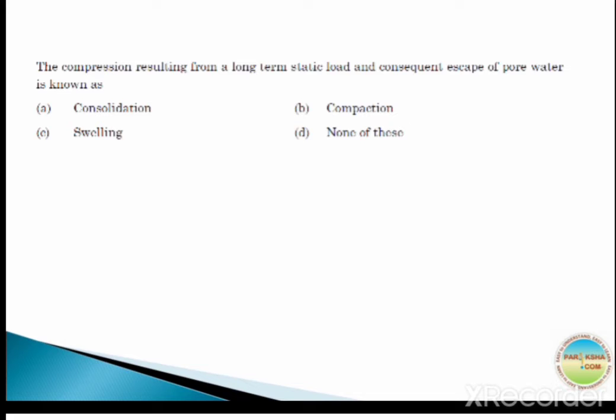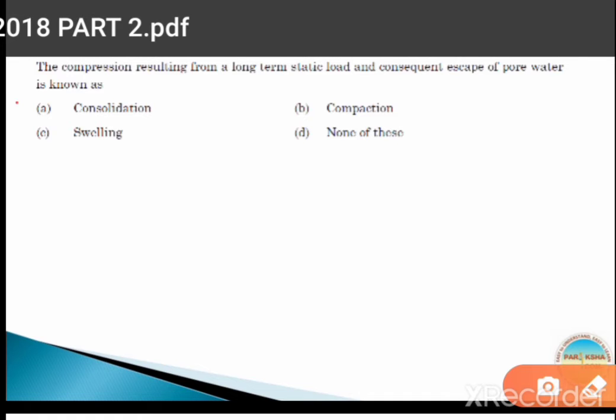Proceeding to the next question. The compression resulting from a long-term static load and consequent escape of pore water pressure is known as. The correct answer for this question is consolidation. The process of consolidation begins when the soil reaches full saturation, and it occurs after expulsion of pore air and remains saturated during the entire process, and also it's a time dependent phenomenon.